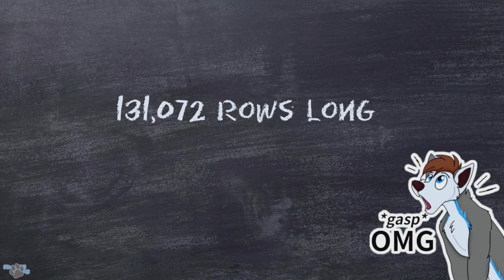Full adders can be strung together if you link the carry out to the carry in of a new one, allowing us to count in different bit ranges, like so. This is an 8-bit ripple adder. I will not be attempting the truth table for this, as it would be over 130,000 rows long.